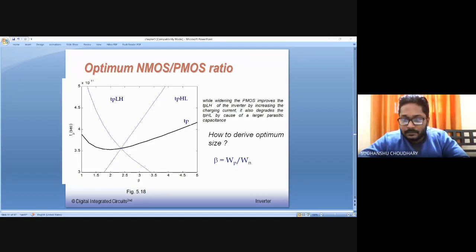Sir, and VDD also, you said we have to give 100 millivolts like that. So how much lower VDD is possible? Yeah, we saw that even at 0.1 volt and even at 0.05 volts, the CMOS inverter characteristics were still shown, right? So how much should VDD be scaled down so that the circuit is free from any noise, thermal noise especially, or maybe system noise, so that it does not affect the performance of your inverter? The recommendation is that VDD should be at least a couple of times 5 kT, that is somewhere around 100 millivolts.